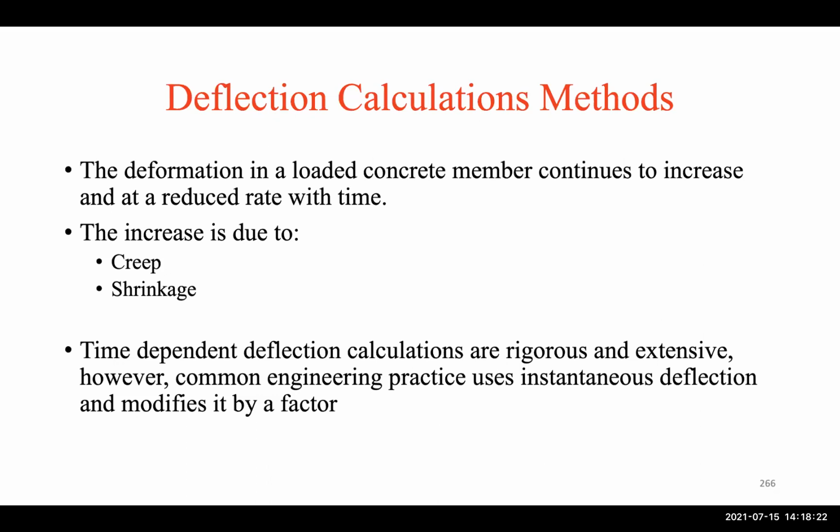We typically start by evaluating elastic deflection, but that increases, of course, non-linearly due to creep and shrinkage, which we are familiar with from reinforced concrete. It's the same thing. These are time-dependent deflections that we have to consider.